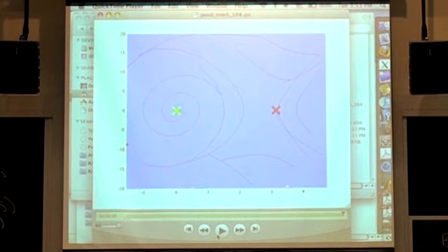Yeah. Could you factor in actuator limits into the Lyapunov function? Yes. So okay, actuator limits in the Lyapunov function are harder. What you do is everything is based on a Taylor expansion of the dynamics around the nominal. So with a hard limit, if I linearize and I don't see that limit, then I'm not going to know about it.